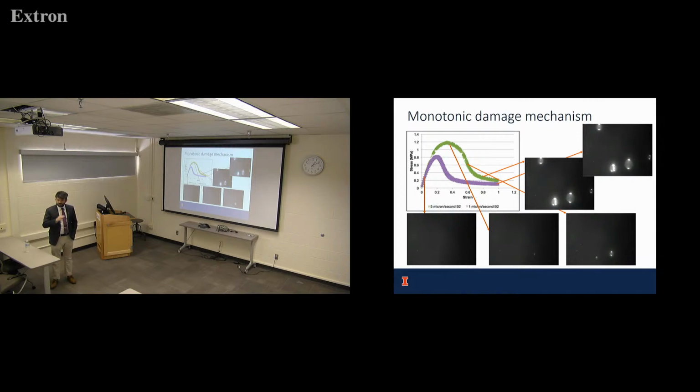But also the model uses linear viscoelasticity first. So we're not thinking about triaxiality. Mostly the effect is going to be on the nonlinear side more. The state of stress is going to have more of an effect towards the nonlinear side than the linear, from what I've read, in terms of ductility, right? So this is going to be mostly post-peak behavior. So that's why we said, okay, it's good enough to assume the linear viscoelastic.